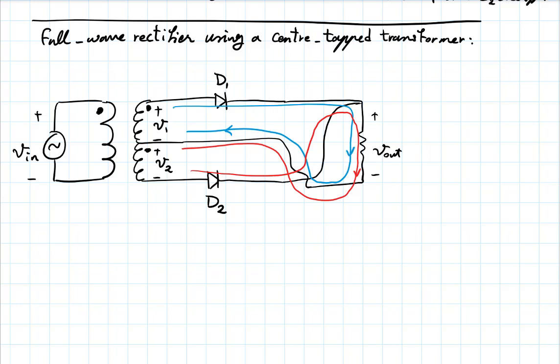So this is also a full wave rectifier. Is there any advantage for this circuit compared to the previous one that you guys can think of? There are 2 diodes instead of 4, but maybe I need a more sophisticated transformer. Right? So there's a trade-off.